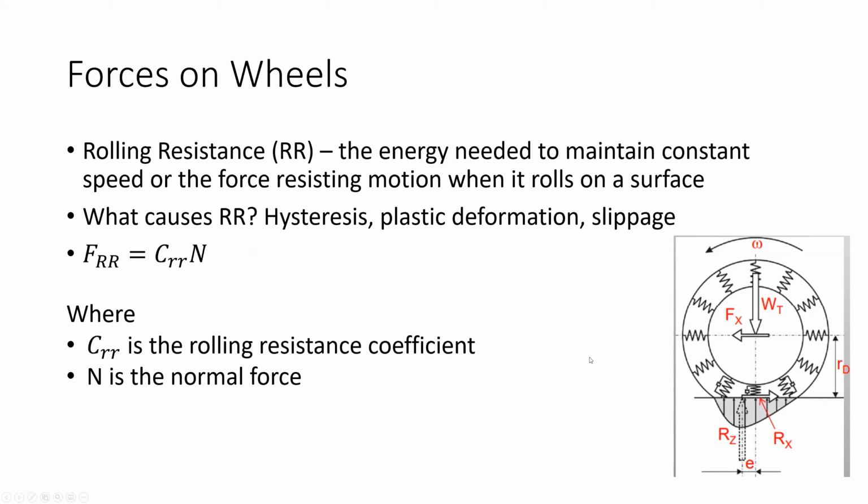And when you're going up a slope, the forces change. If you want to get the axle loading, you would need to use this equation, because since the center of mass is here, you just take the moment about, let's say, this point here to find your force here.